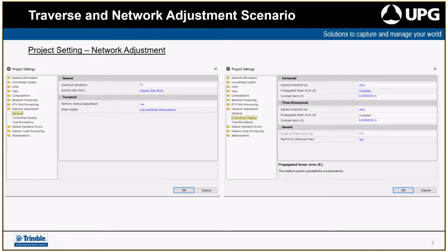an outlier. So if you've obviously turned 6 rounds, if you're an RMS surveyor here in New South Wales, you might turn 6 rounds to everything, and you might want to throw one of those rounds out because it's throwing everything else out of the ballpark. So you might tweak that, and then it'll help your adjustment in the statistics down the other end.